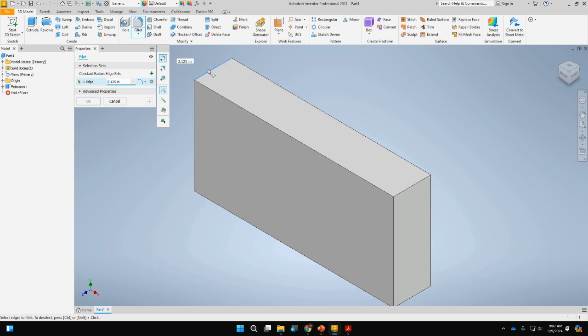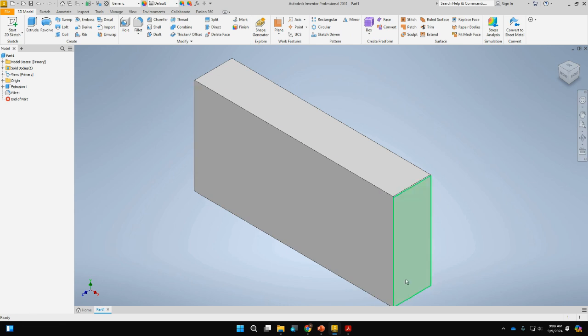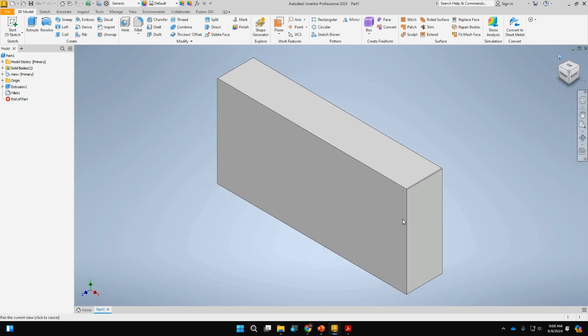and I'm going to select the edges first, just because that's kind of the order, right? So there's 4 edges, and then this is 0.01. So it's just a little, basically in the machining world, that little fillet around the edge is going to just knock those corners off, so that if this was an aluminum block or something, it's not going to be sharp. So we'll click OK. All right. So now we have that in there.